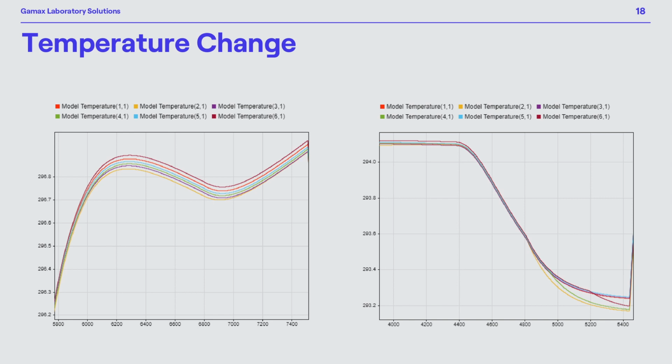So this phenomenon is due to the following fact. We are applying cell edge cooling for the battery module, and our battery cells have different coordinates relative to the edge cooling. So it is natural that we will have a slight difference in the temperature of the cells. This is due to the fact that we have the modeling of the different coordinates of different cells. So this is how you can get different temperatures for different cells.